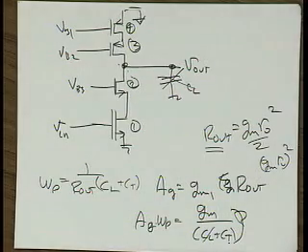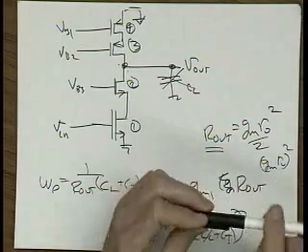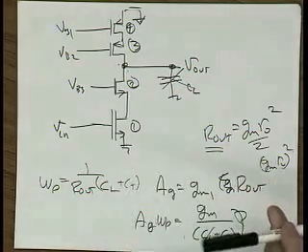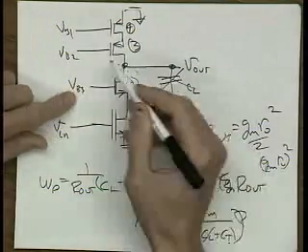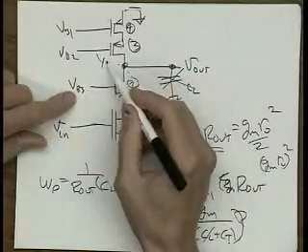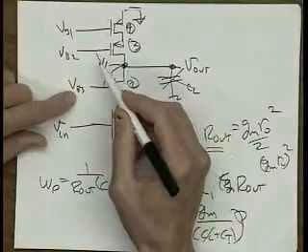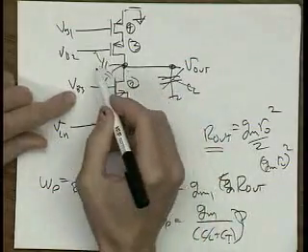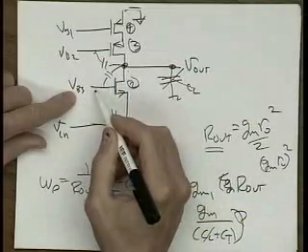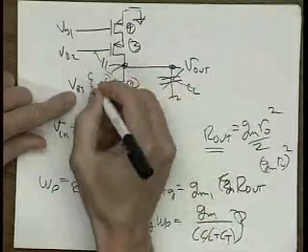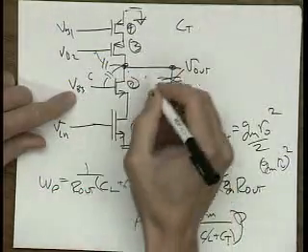How come the capacitances of the other transistors don't come into account, because they're now in the signal path? Which ones now? When you didn't have the cascode, you had, these now will be the important ones. This will be the CT. It'll be this capacitance plus this capacitance will now become the C. So let's call the CT for this circuit going to be